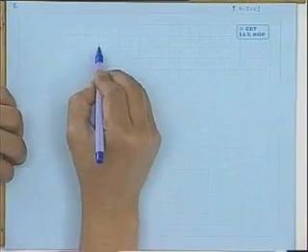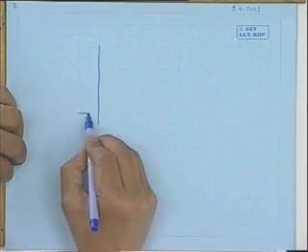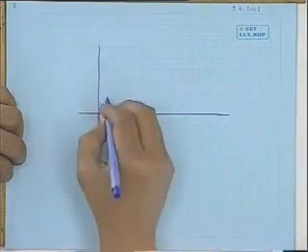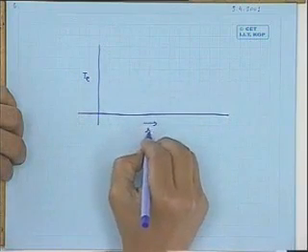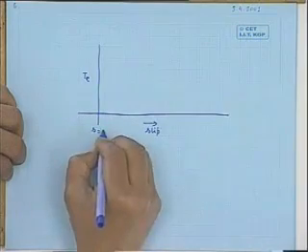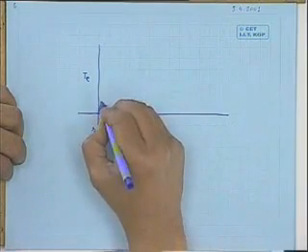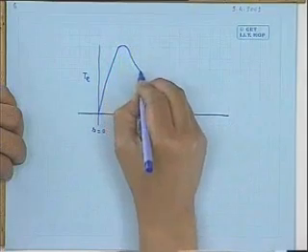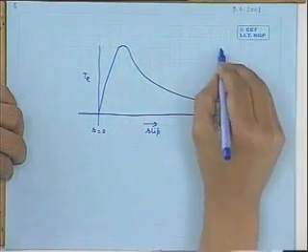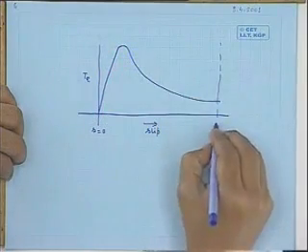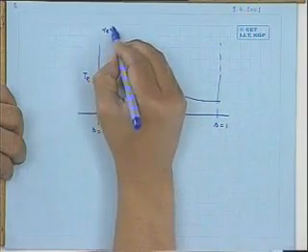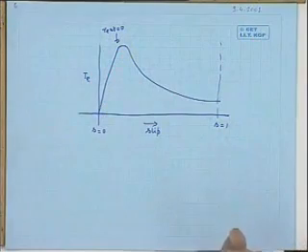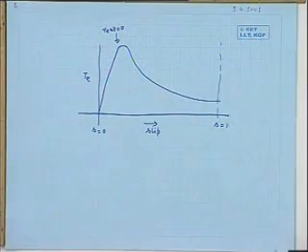then will you leave the resistance in the circuit? What I mean to say, suppose the problem is like this, that you have got the inherent torque slip characteristics of the machine. This is S equal to 0, and this is, suppose, with no external resistance connected. This is the torque slip characteristics of the machine. This is S equal to 1, standstill condition. This is with R external equal to 0. No rotor resistance is connected.